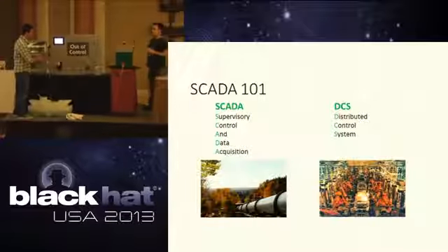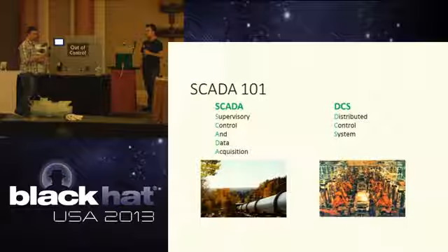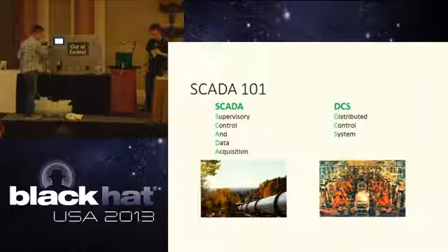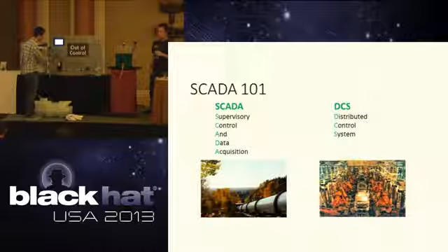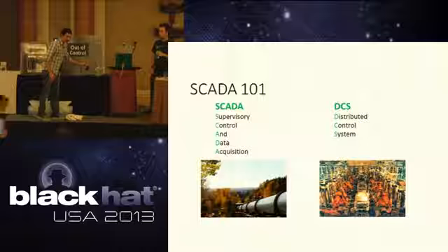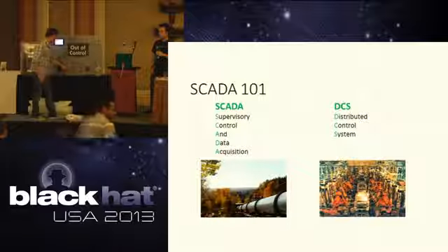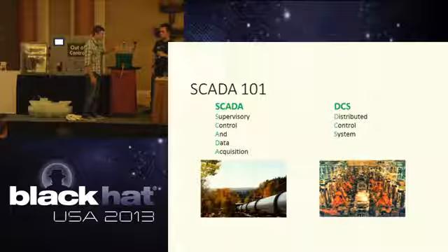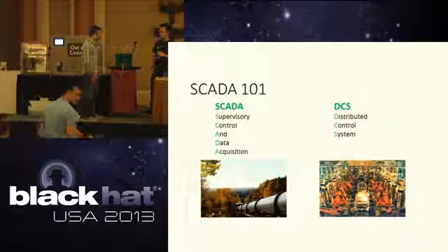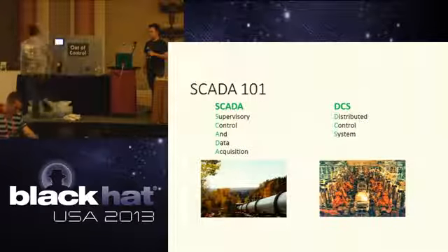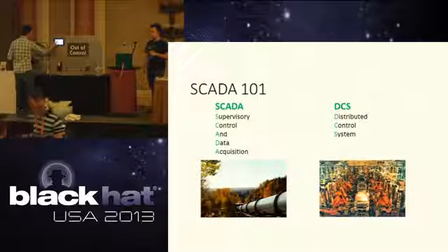Exactly. So what we're going to show is just how the system is supposed to work, right? The way that we've designed this and the logic that's actually in the controller itself, we turn on the pump, we make sure that this isolation valve is open, because if it's not, we end up overpressuring right here. We also make sure that when our level gets to 100, which is about 3 inches below the top, we shut off the pump as well. So these are intrinsic safeties that are inside of this controller itself. So we can quickly demonstrate.